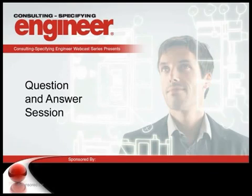But the other thing I would note, I don't know if we can go back to that slide, is that even though there is instantaneous overlap shown, the generator fault output can only put out as much as the decrement curve. So whereas it's overlapping, it actually doesn't apply. So it would selectively coordinate perfectly.